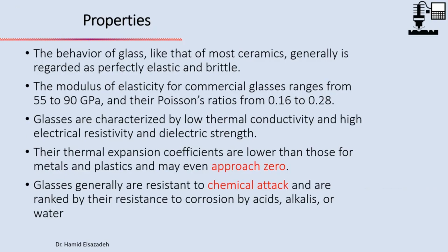Let's look at the properties of glass. Glass is similar to ceramic generally, and they are brittle materials. The modulus of elasticity, or Young modulus, is between 55 and 90 gigapascal. You remember the Young modulus of the metal steel is about 200 gigapascal, right?